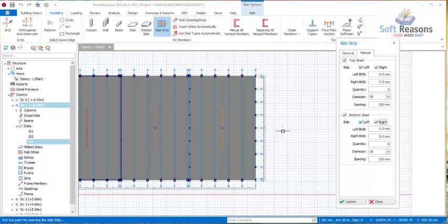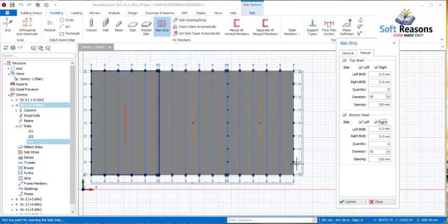Now if you are designing for both top and bottom, all right, but we are to be designing for just bottom reinforcement, so we really don't need top reinforcement because this is just a weightless slab which is not carrying much load apart from human traffic load within this area of this warehouse. Okay, but I want to show you this as an example.